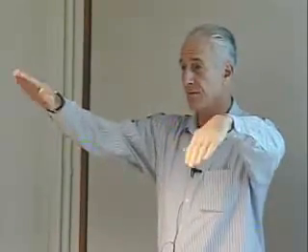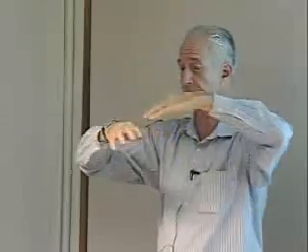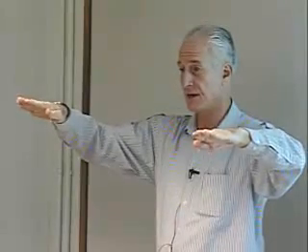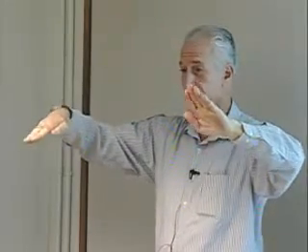The fuel cells are generating all of the power. The guidance, navigation, and control is being done inside the shuttle, and the results are sent to the solid boosters. The solids' gimbals can move. So the roll maneuver, for instance, is done by the solid engines.